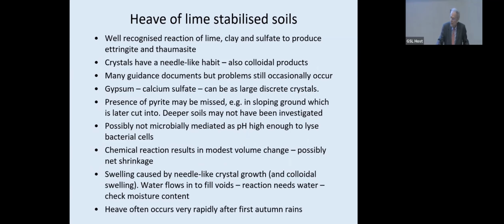Heave of lime stabilized soils, that's really the same reaction, different problem. We know all about stabilized soils. It's a very economic process: mix lime and clay, you get a good strong material. The crystals form a needle-like habit of reaction products between clay, sulfate, and lime. They can also take a colloidal form. There's lots of guidance, but one of the problems is if you've got, say, gypsum in the soil, which can be quite large but discrete crystals.